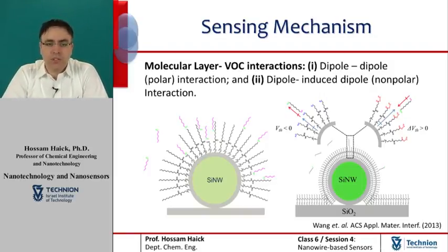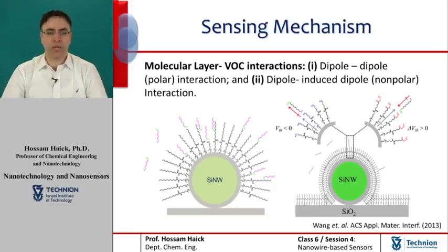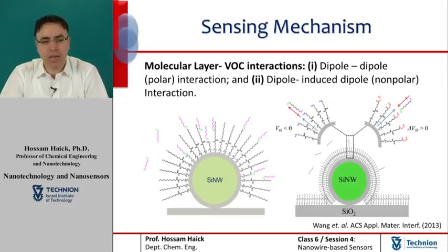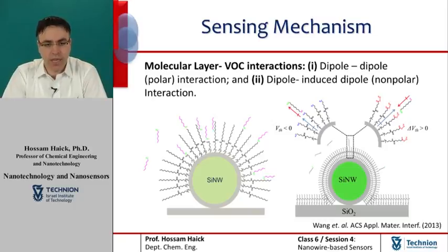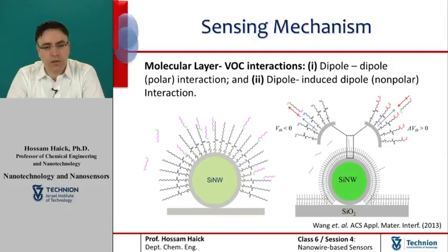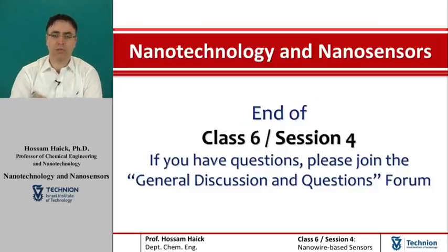Furthermore, the large intermolecular space of the long-chain molecular layer, which is due to the longer chain length of the molecular layer and due to the low second layer amide interaction ratio, enables it to adsorb more gas analytes than the short chain molecular layers, and thereby this increases the voltage threshold response to the gas analytes that are examined. In addition, it's likely that the diffusion of the gas analytes into the molecular layer, determined by the type of the functional group, is the main reason for the Hall mobility responses.